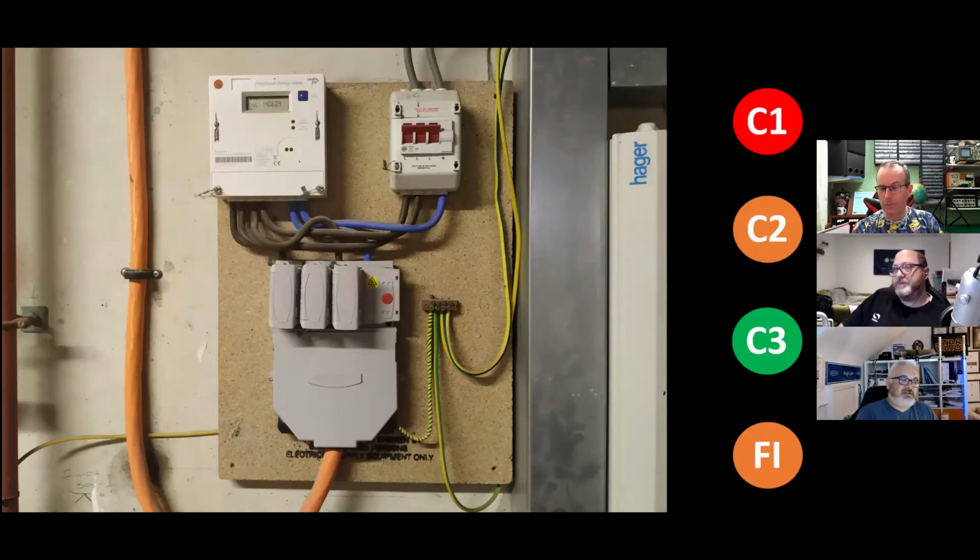What's this installation? Identifying the supply type. This is a GRP cutout. It is a brand new concentric cable, 3-phase isolator. Can anybody see any issues with it other than obviously the supply type? Is there anything else you can spot? Two phases. Yeah, look carefully at what's actually connected to what here, because it's not what you might assume straight away. Damn you, John. Right, go on, John. One phase coming out.